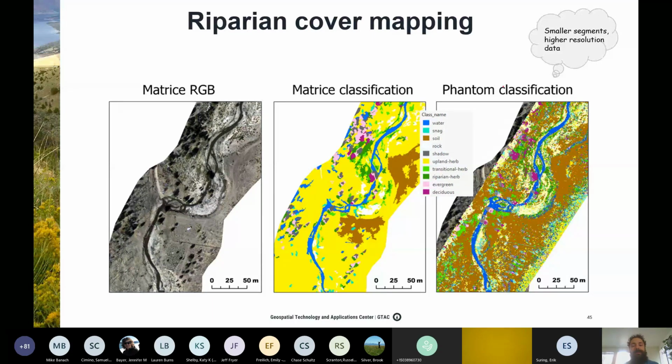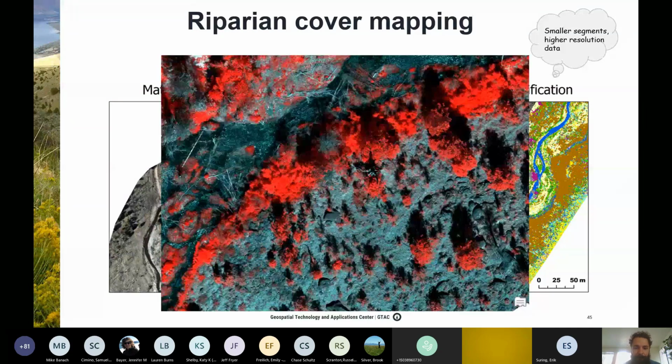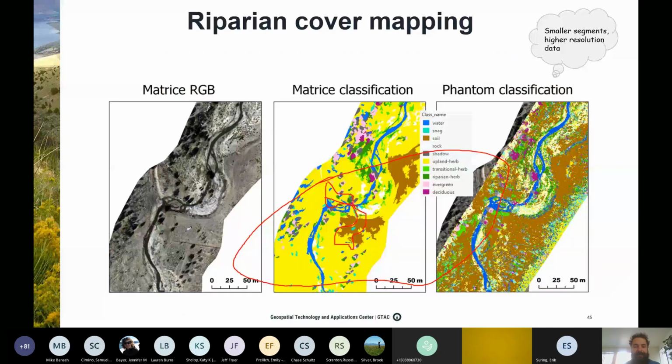This difference is important because when Lena was doing the analysis, she did not take that into consideration and kept the scale parameters the same when we were conducting this analysis in eCognition. So, for example, in the higher resolution imagery, what was happening was the soil in between this vegetated area was being classified as soil. Whereas in the lower, coarser resolution imagery, this area would have been classified as upland woody vegetation. And that's why you see this change in distribution of the land cover types.